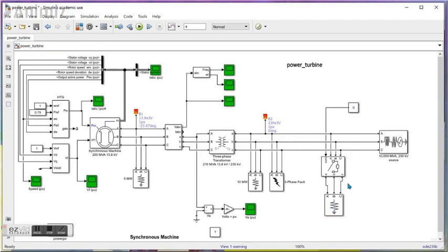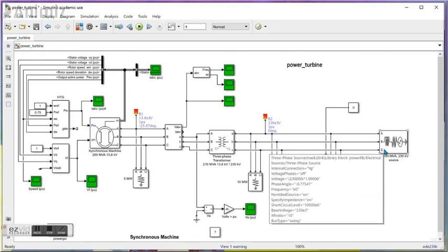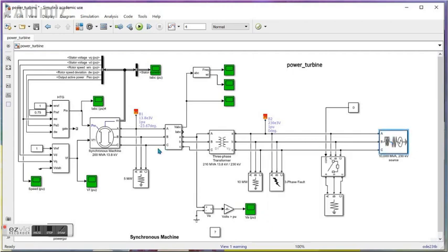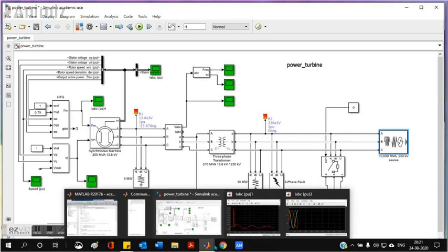And the droop control, we don't have to do anything about it because the machines in MATLAB, like the Synchronous machine here, already have droop control in their backend, so they will automatically adjust to the change in load.